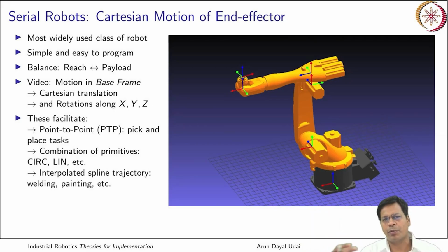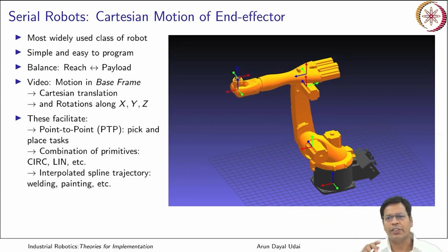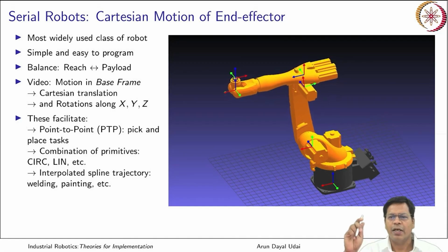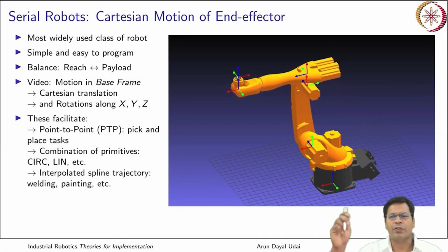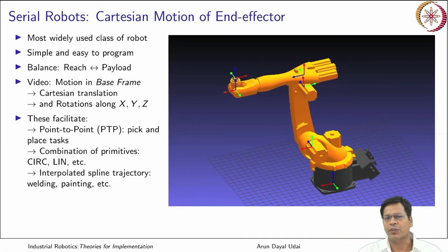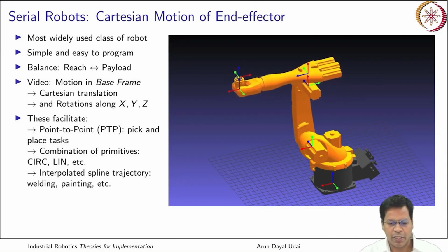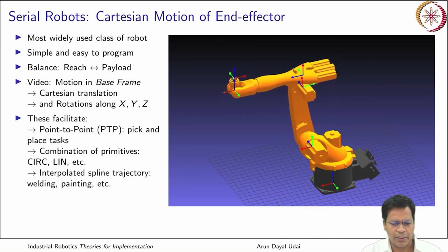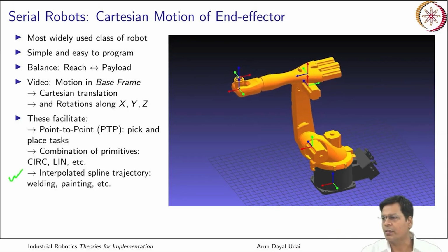When we program, I don't just mean it can go point to point only in position. It will continuously and gradually shift its orientation, which was taught at every location in the workspace. So that is how it can be programmed. This kind of programming is already fitted into this kind of robot's controller.